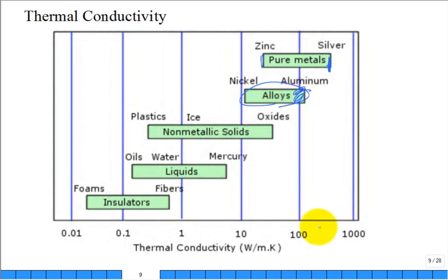This is a plot just showing you a recipe to build a good insulator: get air to be stationary. That's it. So what do you think the spun fiberglass is that you put in home attics? That's glass. That's actually a pretty good higher K than the air. Why are you putting fiberglass in the air? It seems like that mixture is going to have an overall higher thermal conductivity. Well, it's holding air stationary.